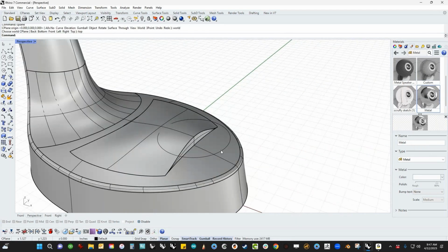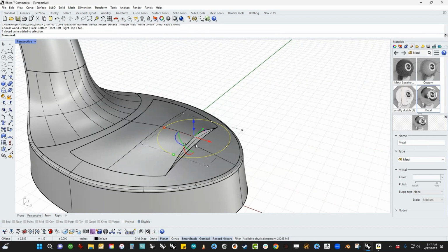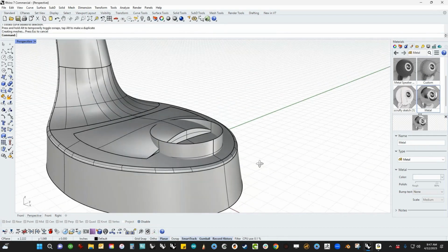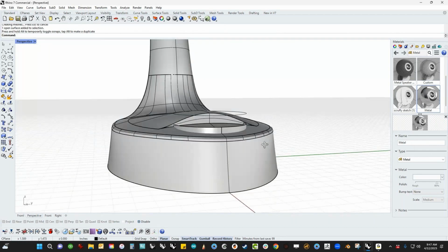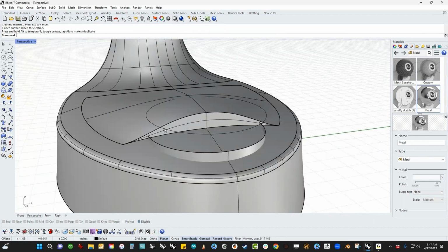I'm going to click it. I'm going to drag the extrude dot with gumball to get some shape. And then I'm going to just position it somewhere kind of in there. Now, I would like to have this button have a similar kind of dome to this shape.